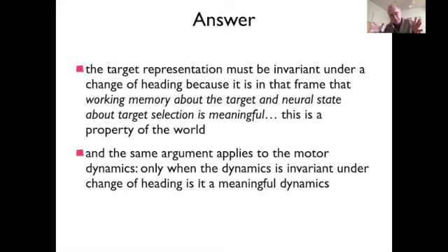It's the fact that the dynamical system as such has to be invariant under the initial position of the robot. So if you were to try to write down a dynamical system for the robot moving in terms of robot-centered variables, where you take the deviation from 0 as the behavior variable, then the state would always be 0 because the robot is always heading wherever its nose is pointing.